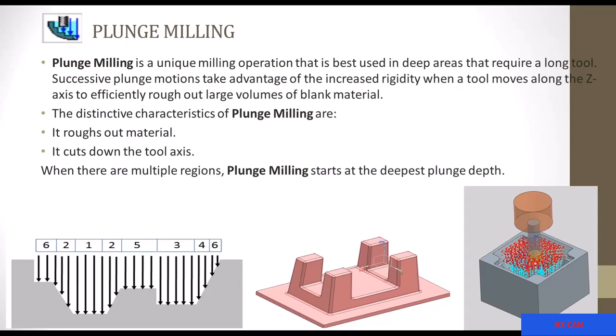Yes, today we will see plunge milling. Plunge milling is a technique where with the help of a long tool we can cut deeper areas in the cavity, right? So here you can see, first it will cut the deeper area, then a little bit shallow, and then the upper area, right? In this way it creates the tool path in deep cavities.